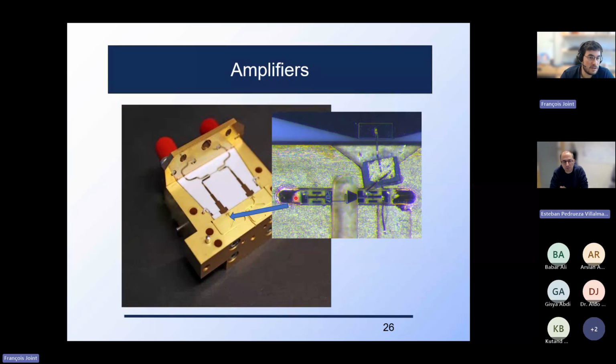We think we have enough good tools in the cleanroom, from lithography to sputtering to dicing techniques. Something as easy as dicing that people can imagine actually becomes quite difficult for us, because we need to be precise within a few microns in dicing. The substrate thickness is very narrow, only 65 micron. To manipulate that is a challenge. After years and years of development, we are good at that now. But now the issue is the integration.